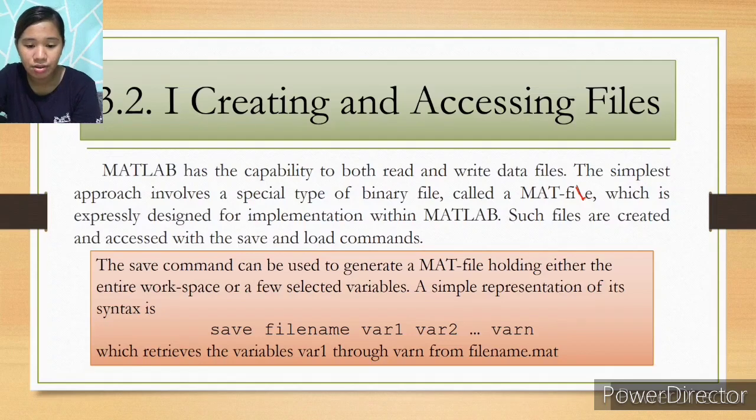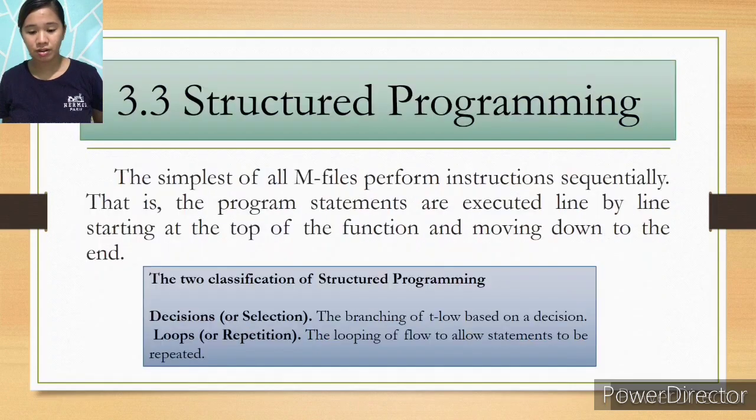The save command can be used to generate a MAT file holding either the entire workspace or a few selected variables. A simple representation of its syntax is save filename var1 var2 ... varn. The load command retrieves the variables var1 through varn from the file filename.mat.